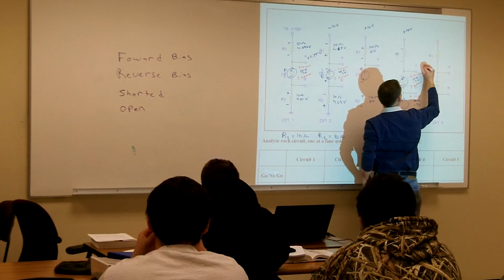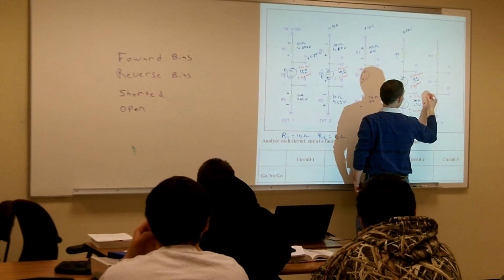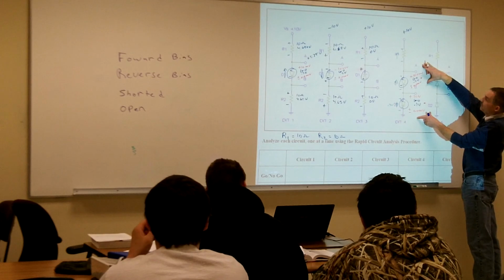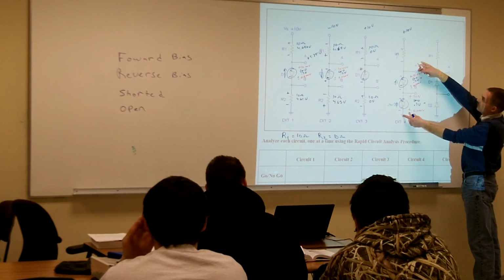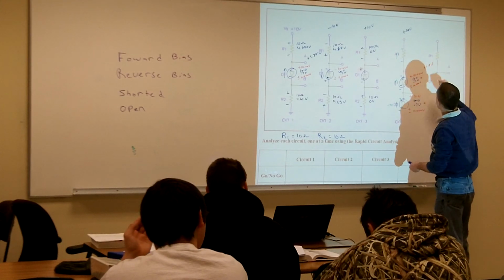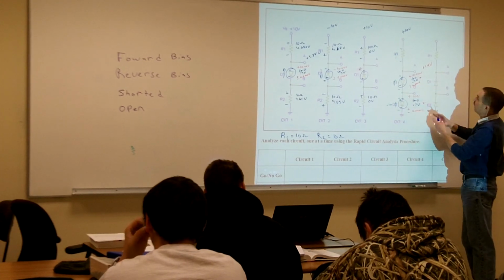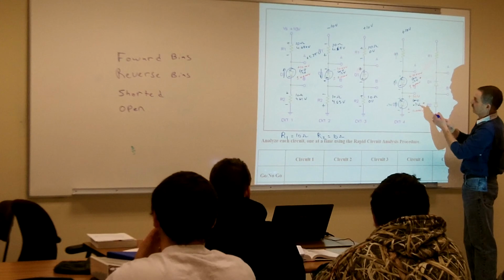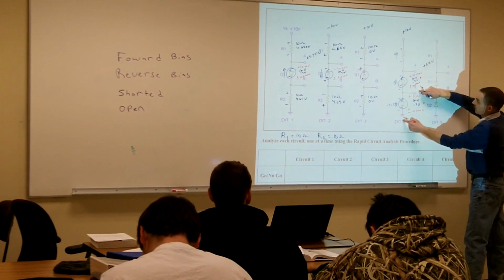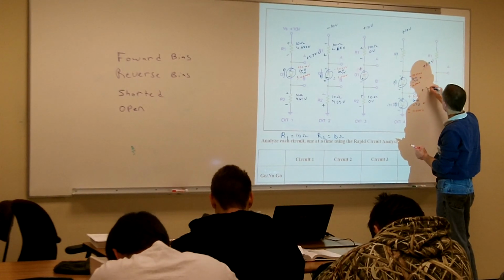Yeah. So each diode is going to drop 0.7 volts, right? So if I'm measuring across the two diodes at test point A, I'm going to measure a positive 1.4 volts. On test point B, keep that blue because that's a hard one. At test point B, what am I going to measure for voltage? Plus 0.7 volts.